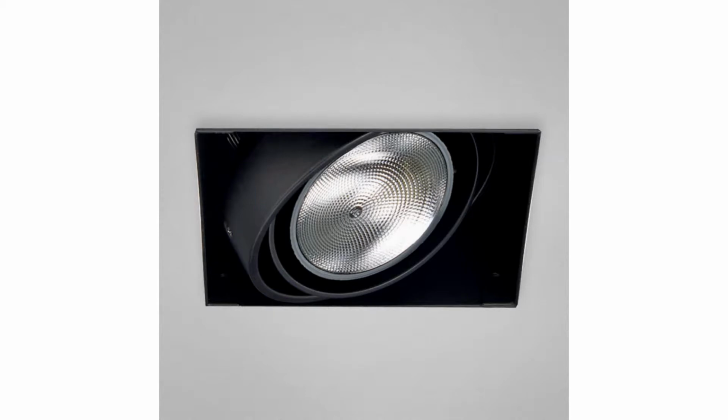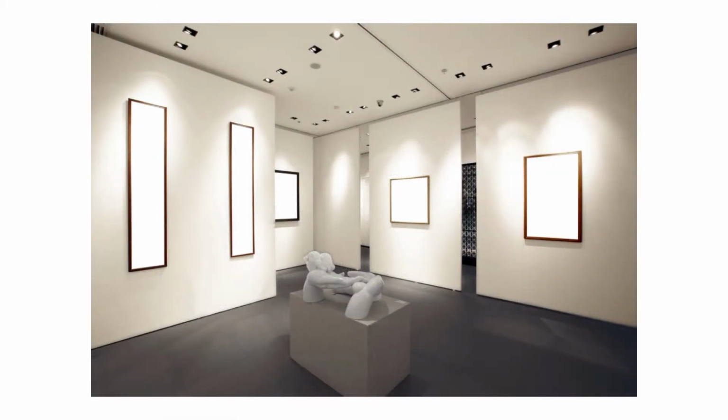Again, when you have an adjustable light, you want to make sure that the luminaire itself is dark enough and has enough baffling ability to keep you from seeing that bright light source. And here's a gallery. I think that the photograph actually does show a bright spot right at the center of the ceiling, but the ceiling is high enough that we are not really bothered by the whole bright area. But you can see that the paintings do appear to have pretty even blobs of light on them.